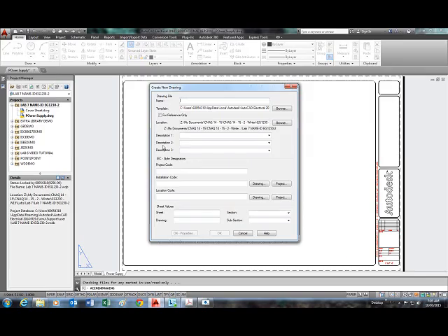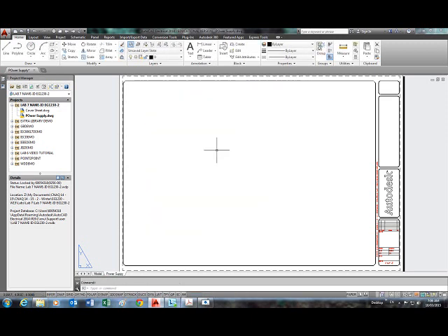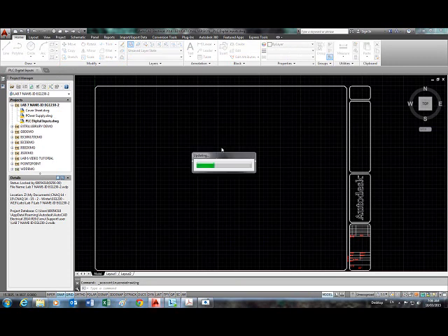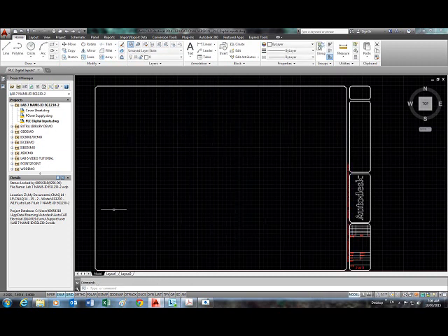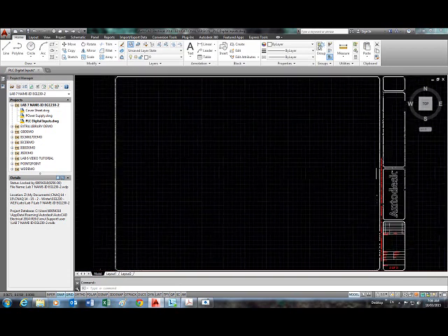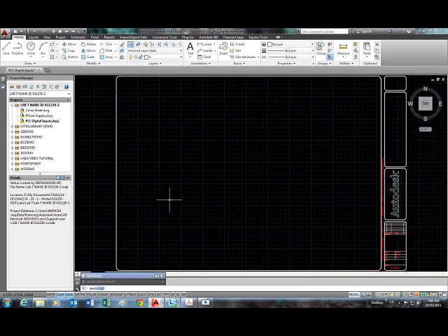The next drawing is PLC digital inputs, and this is sheet number 2. You can go to OK, properties. We don't need to, because every drawing will inherit the properties that you have set up for the project, but you can check them if you want, and there are the settings that we have previously chosen. So we don't need this. We'll go again, double click the wheel, center, nav cube off,